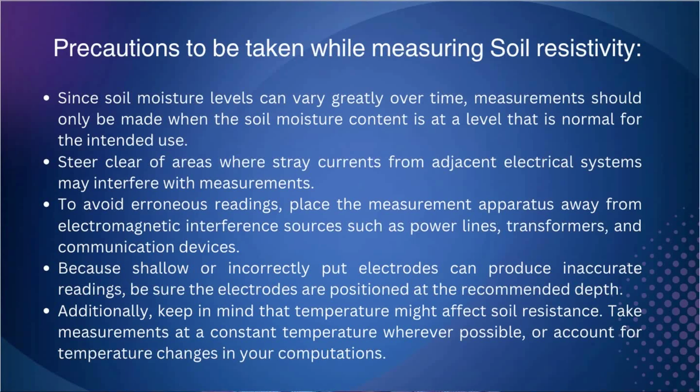Next, to avoid faulty readings, place the measurement apparatus away from electromagnetic interference sources such as power lines, transformers, and communication devices. Additionally, keep in mind that temperature might affect soil resistivity. Take measurements at a constant temperature wherever possible, or account for temperature changes in your computation.